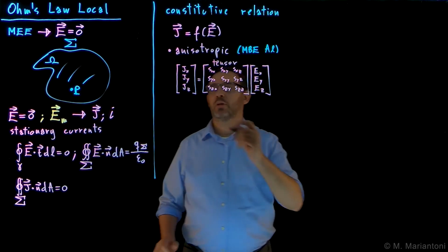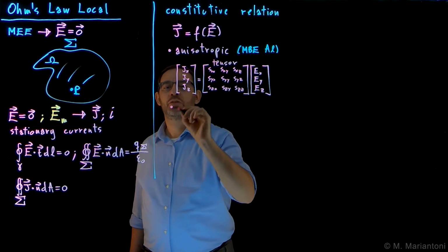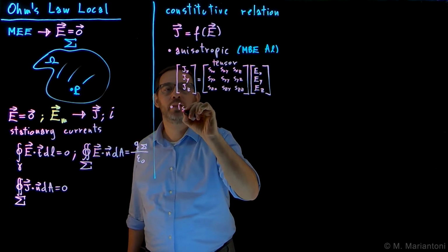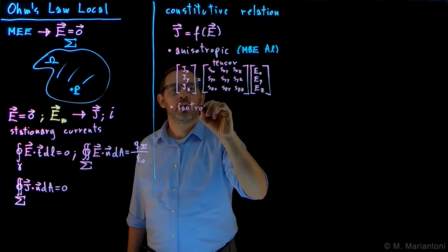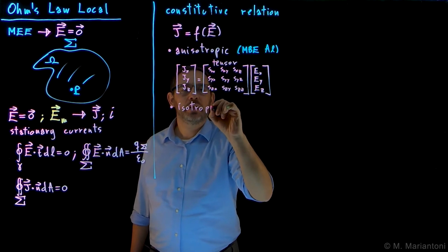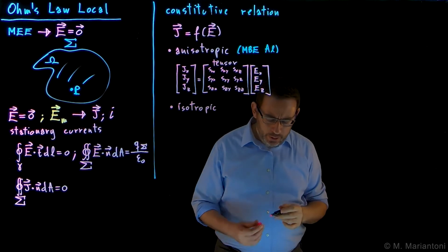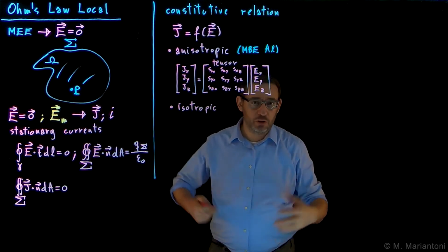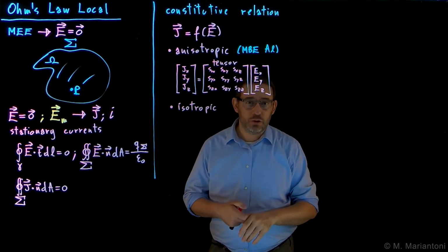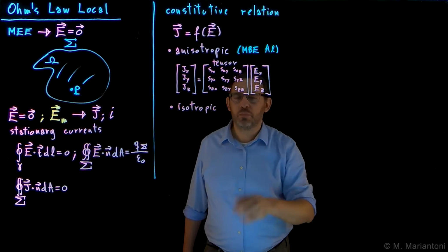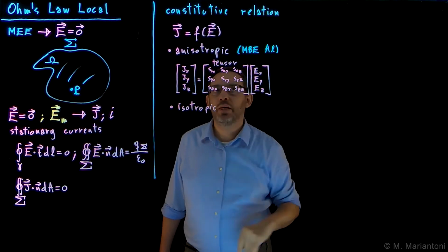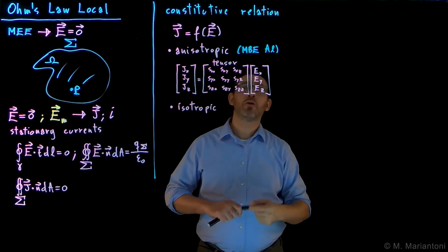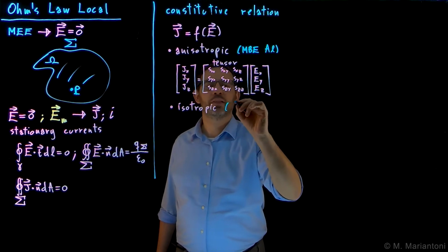The simpler case we are going to consider in this course, which is very common, is isotropic materials. For example, if you take an e-beam, an electron beam evaporator, or a thermal evaporator, where you heat up a piece of aluminum and it evaporates over a silicon substrate, you don't get an MBE-like material, you get an isotropic material.